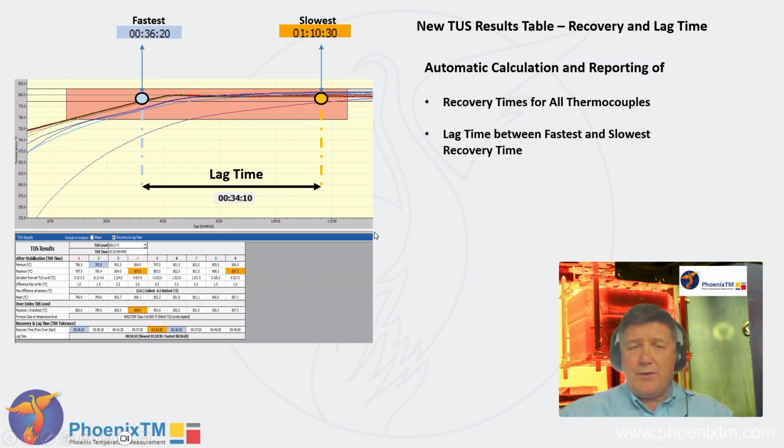So the only thing you need to do is to adjust the oven start to ensure that you've got consistent data reference in terms of time for when the product was loaded into the furnace and the survey was started.